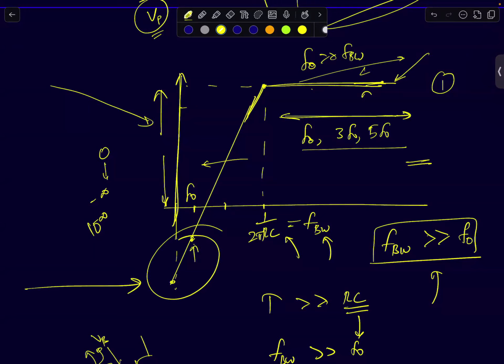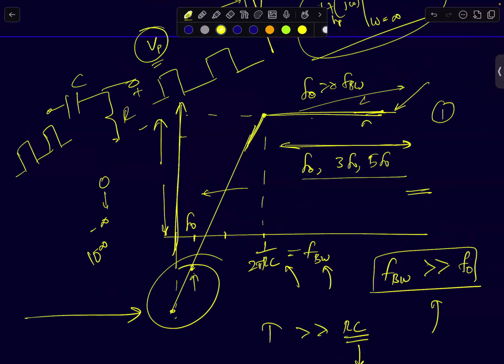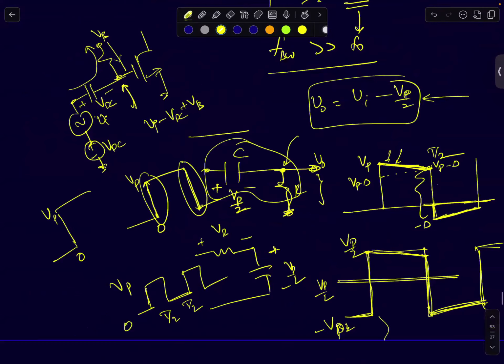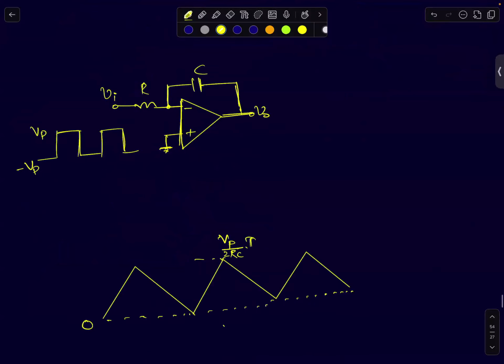That's what's happening in a high pass RC circuit. I'm removing all the DC content alone and passing the AC signal. I'm calling it AC, but it's the DC removed signal, which oscillates between negative and positive values. That's how we interpret an RC circuit. I wanted to discuss integrators, but keeping this in mind, I'll start discussing practical integrators.